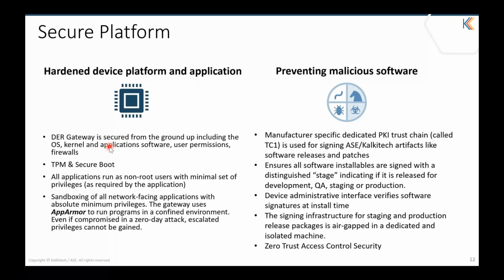And it can also have different stages associated with the firmware which is getting loaded into the device, like developer, QA, staging or production, so that it ensures a firmware released for testing, development or QA will not be used for a production deployment.